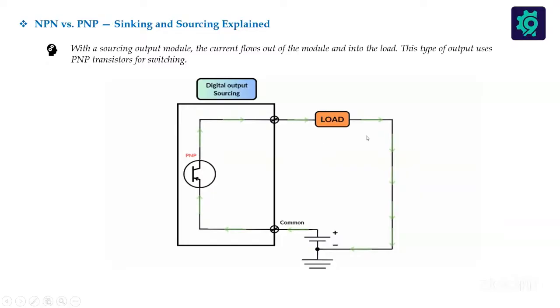In this case now, your load is sinking into the PLC, because when you look at the flow of signal, how it gets into the PLC, this is the flow of signal from the load into the PLC. So in this case, it's sinking into the PLC, while in this direction it is sourcing from the PLC, sourcing and then sinking into the PLC.